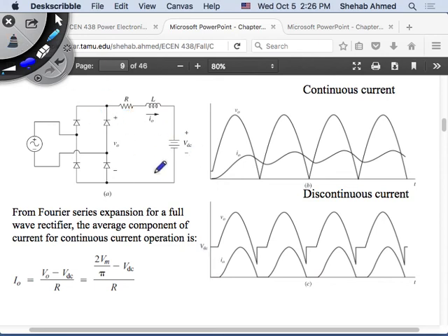So we will see later when we make these SCRs, these thyristors, and we have an RL and a source case, we can make the voltage negative. We can make this output voltage negative, but we will maintain the same current polarity. So I will make the voltage negative. Here I have output voltage. Remember, what is my average output here? Is it positive or negative? The average value of this full wave rectified waveform is a positive value.